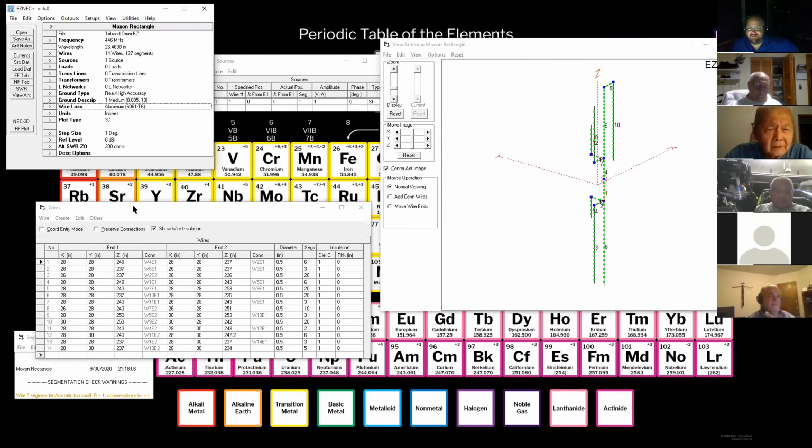Why do you say that the copper-coated iron is so difficult to get? Well, copper-coated steel is easy to get. Copper-coated stainless steel is a nightmare to get. Copper-coating stainless steel is not easy, number one, because stainless steel has a passivating layer. So it's not a commercially available product.